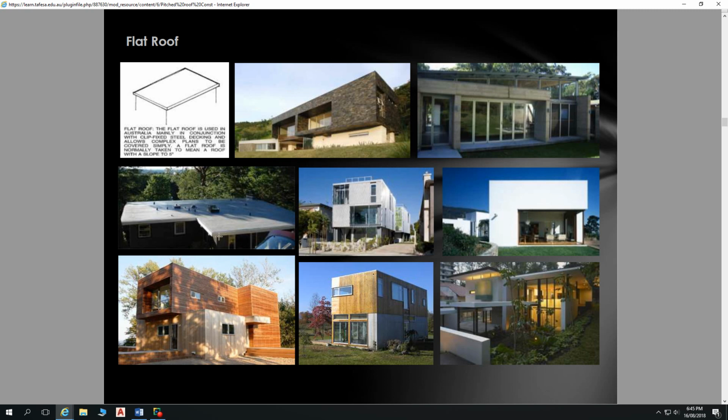Typically, a lot of the flat roofs are enclosed behind a parapet, so that's certainly still very much in vogue aesthetically, whereby you produce a very minimal looking box. So we can have the flat roof, and then we extend the walls up past that flat roof to create essentially a shipping container type look. But it was also quite an aesthetic, particularly in the 60s and 70s, to have flat roofs that are expressed as a flat roof as well.